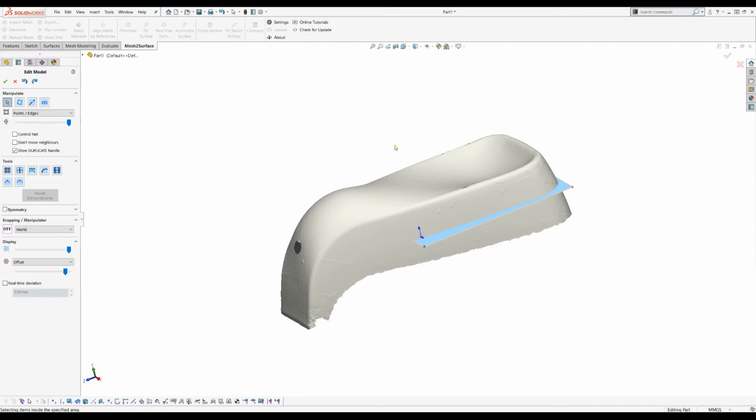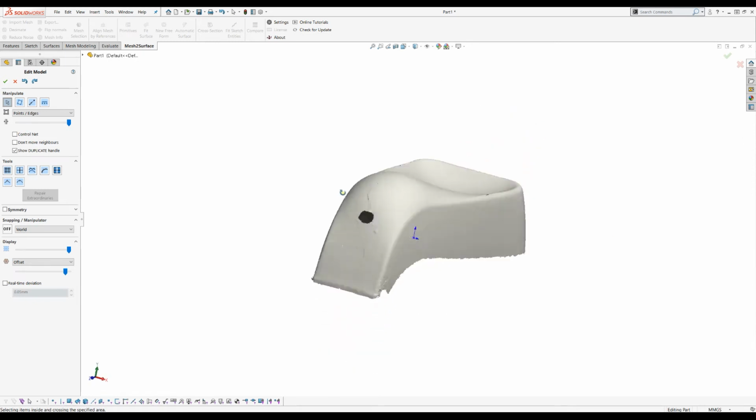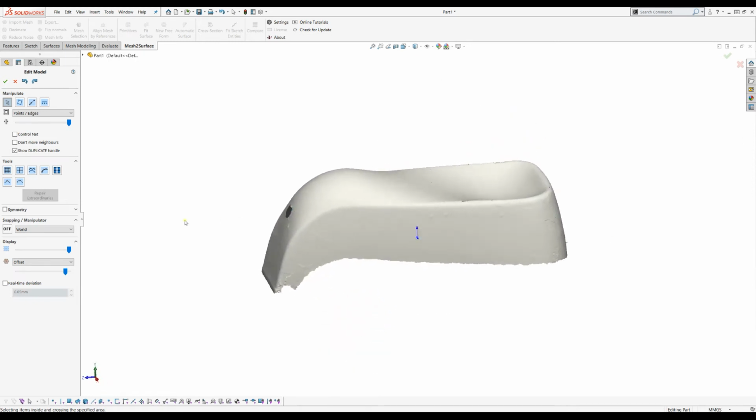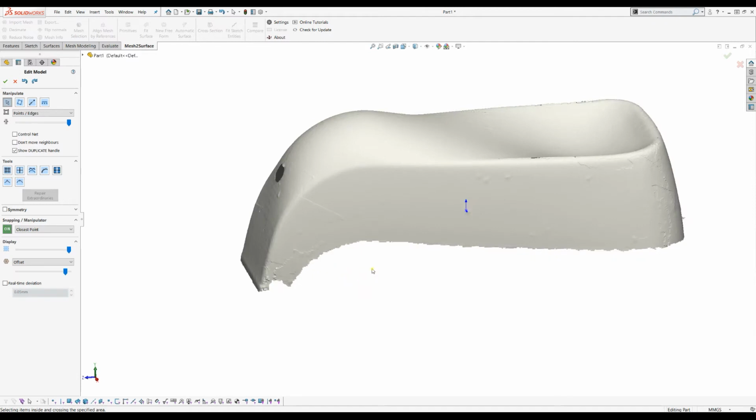This is one of the most powerful tools that will help you to actually reconstruct this. So I will just delete my start face and will place my object comfortable and will make sure that the snapping mode is turned on. This will mean that whatever I do on the screen, the software automatically will place the freeform surface that I create onto the mesh.